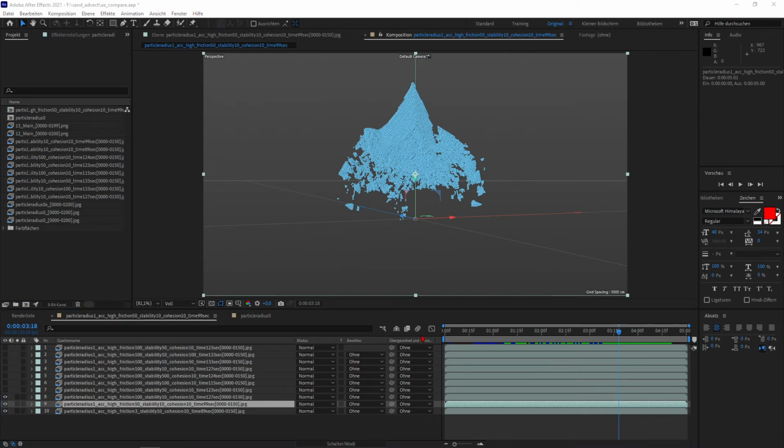And the cohesion, he basically explained like some springy constraints in between these clumps, which will hold them together. So you just think of them like there are little springs, and if you go to a high cohesion, then a clump like this and a clump like this, they still will be connected, and maybe it will come back and you will get some stretchy, wobbly behavior, all right? So just be careful if you go too high with your cohesion. I did it in this upper test here, but overall, I need to start another test series to really get behind these numbers.